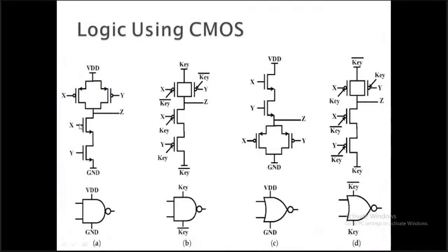so these gates are main. These gates are connected through the metal layer. So these are main gates. So how will this gate be connected? If there are, let's say, 2-3 adders, 2-3 NAND gates, there should be connectivity between this port and this port. It cannot be possible in one layer itself. So we need more layers to connect all these things.